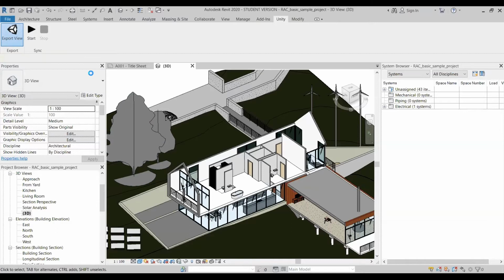We hit the export view and it opens up our Unity Reflect menu. And again, this is now the repo. This is the menu for all of our projects. We can create a new project or we can just jam it into another project. So you see the full workflow. Let's go ahead and create a new project. We're going to do a Reflect Revit Live. And a gotcha, make sure you hit export. If you don't hit export, then it won't actually go through.